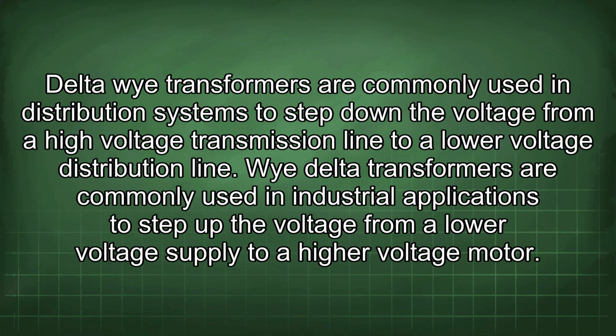Delta-Y transformers are commonly used in distribution systems to step down the voltage from a high-voltage transmission line to a lower-voltage distribution line. Y-delta transformers are commonly used in industrial applications to step up the voltage from a lower voltage supply to a higher voltage motor.